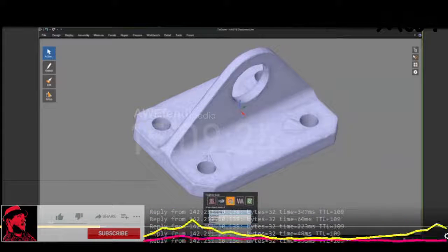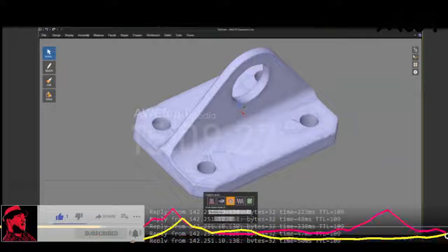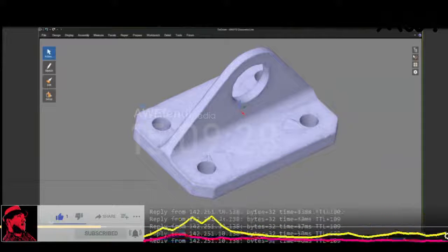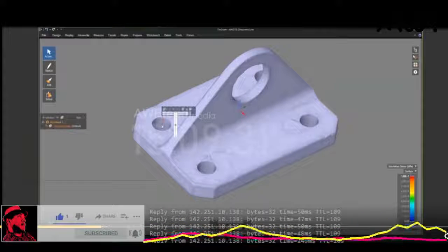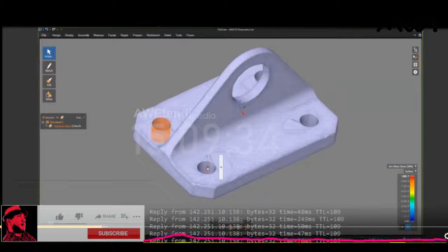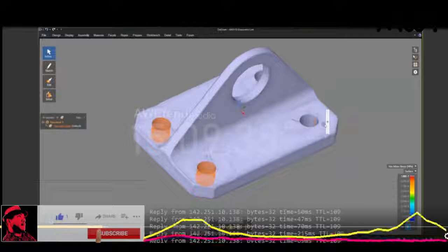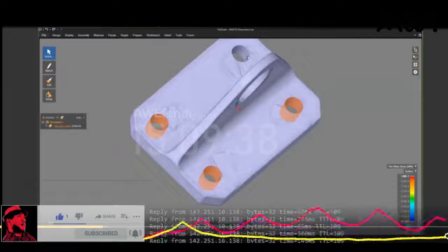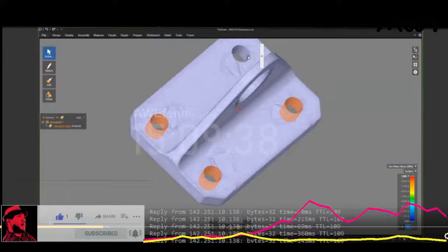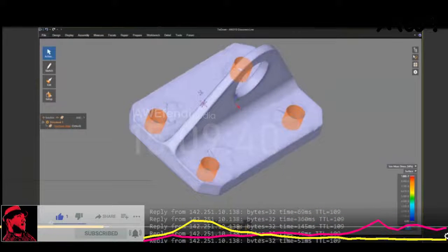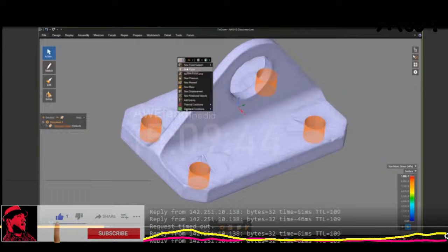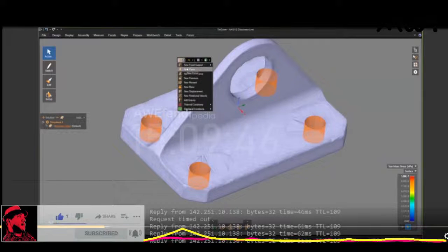So today this thing is a stainless steel part, and it's going to be really quick and straightforward to set up, where I just select these holes right here, and I can easily apply a boundary condition. In the same way that I can select the surface body, I can select these facets. So I'm going to assign a boundary condition. Now you can see all the different boundary conditions that are available when I'm ready to do a structural analysis, right?